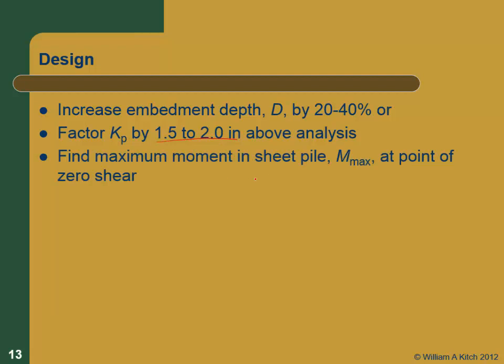Then we're going to find the maximum moment in the pile. We'll draw our shear and moment diagram, and wherever the shear is 0 is our maximum moment.